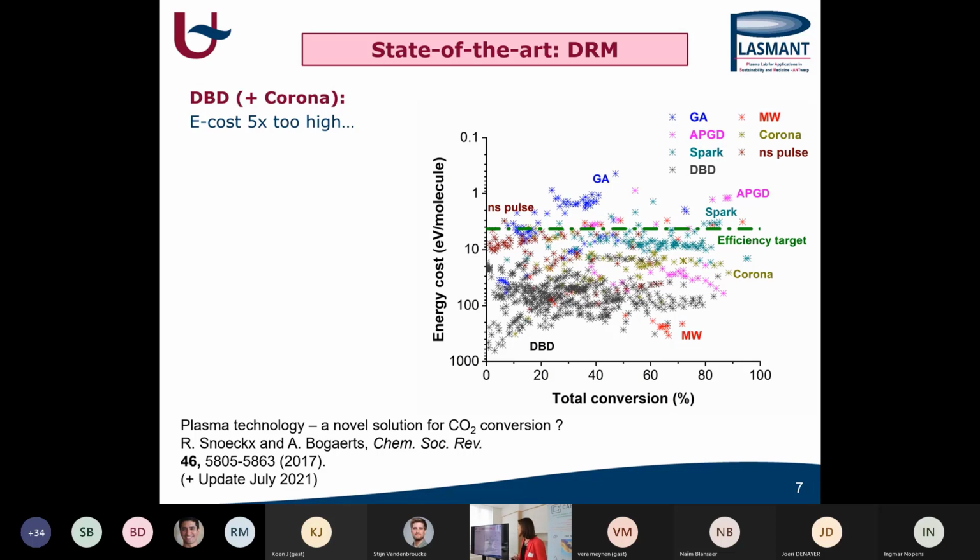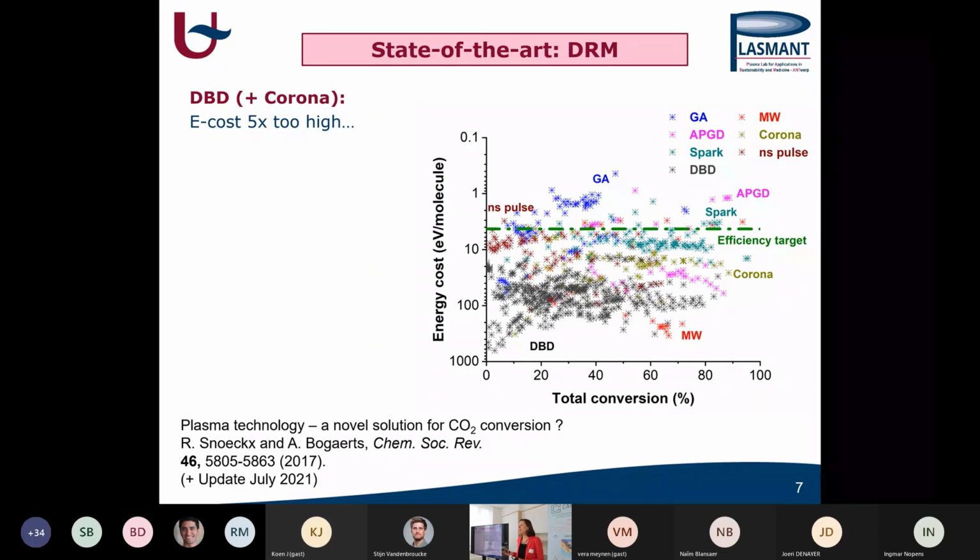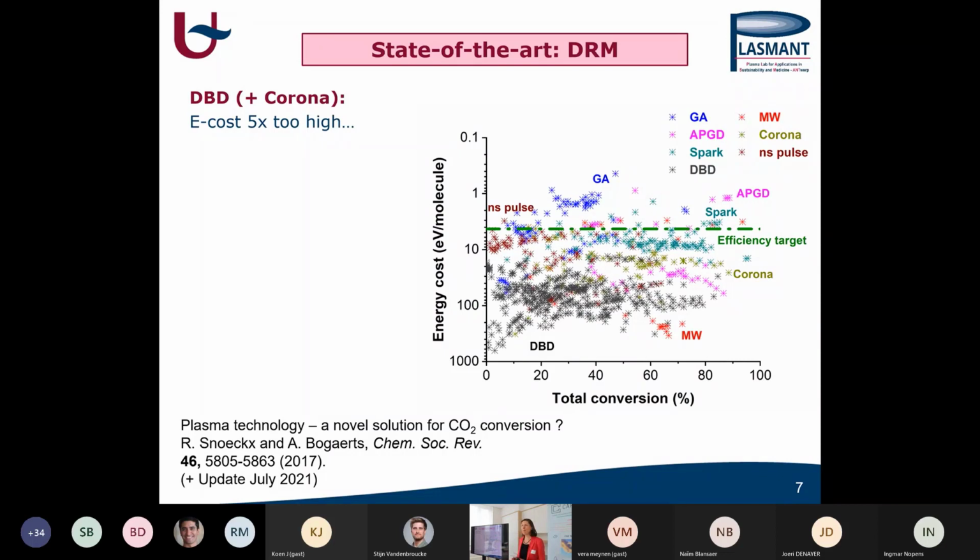Now this is specifically for syngas formation, but a DBD is actually more easily combined with catalysts. And if you can find suitable catalysts that can selectively form, for instance, methanol or other oxygenates that have a higher value, then the criterion is less strict. Then the value-added product has a higher value, and a higher energy cost can already make the process more competitive, because in another process you would need a second process, for instance, to process the syngas in Fischer-Tropsch to create the other products.